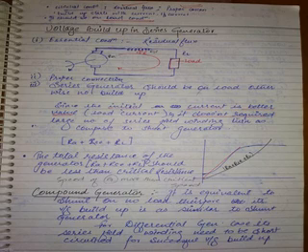The necessary conditions are similar. Number one, residual flux. Number two, some load should be connected across the terminals. Number three, field and armature properly connected.